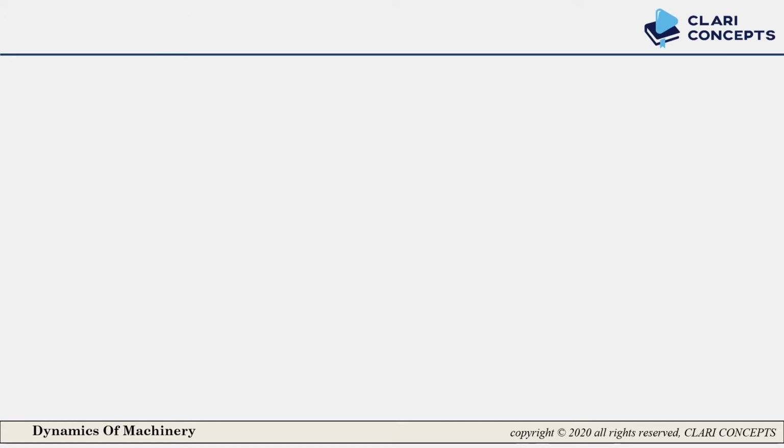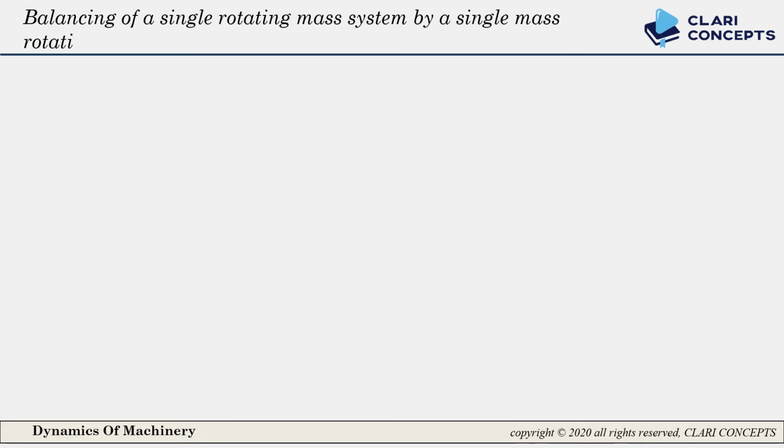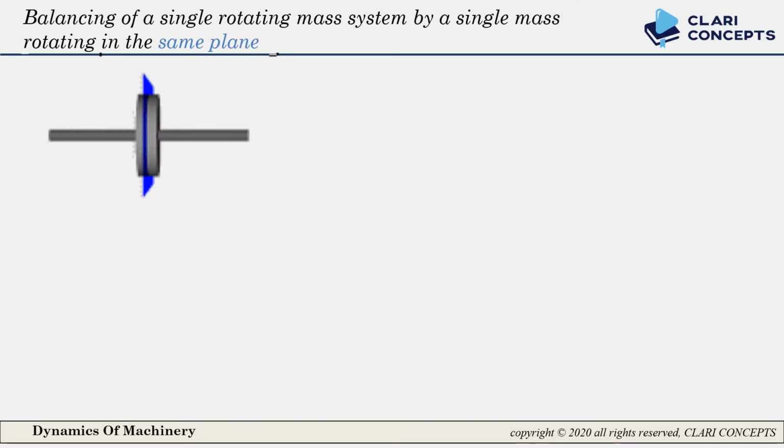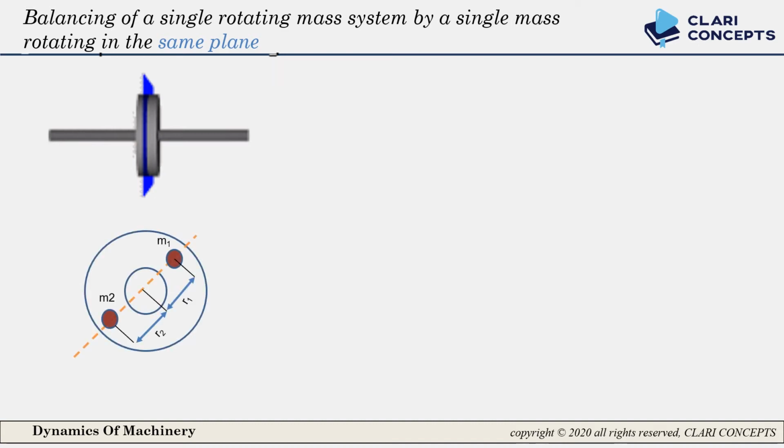As we said, there are two methods to solve any rotary balancing problem. But here we talk about the same plane, so no couple or moment is produced. Now first talk about the graphical method, in which your polygon should be closed to make the system balanced. But in our case, only one force is balanced. To make it balanced, we added one extra mass which creates some force. Due to these two forces, the polygon can't be closed. It will be only one line. For that, we will talk only about the analytical method.